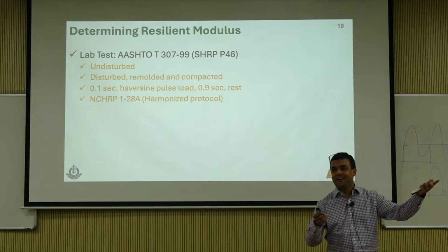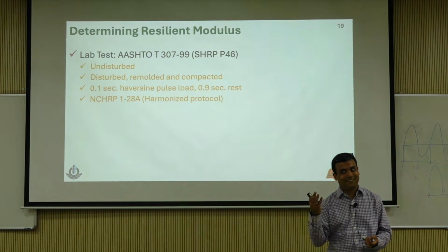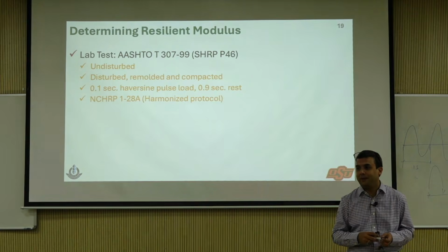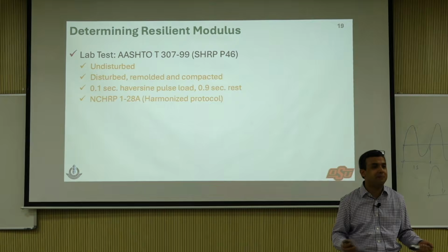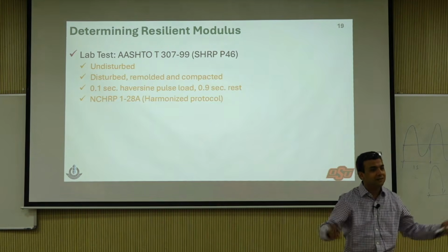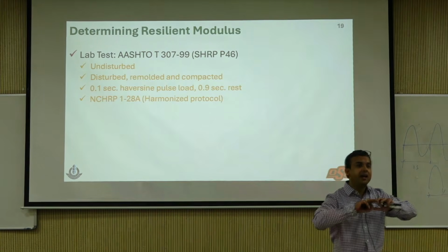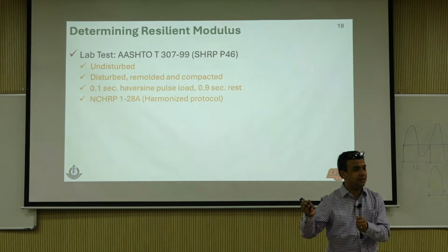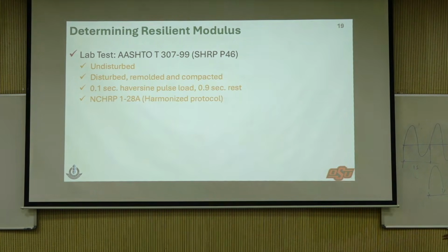Yes, harder does not mean we should not do it, right? It's difficult to get an undisturbed sample, but if the geotechs can, we can too. But the answer I was looking for is that when you are doing pavement construction, you are anyway compacting, mixing, and scraping. So it is always reconstituted, remolded. So it's not really undisturbed in the resilient modulus test.